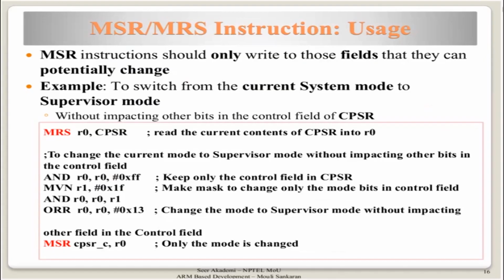So welcome back. I hope you already understood what is happening here. These instructions are all executed one after the other. What happens here? We are loading the CPSR into R0. Please remember, when you are using the MRS instruction to access the CPSR, you are not mentioning the field. It is only when you are writing into them. So here you can say I am interested in reading the CPSR or SPSR based on which mode you are running this instruction from, and it will copy that value into one of the general purpose registers you mentioned here. Now the CPSR value has come here.